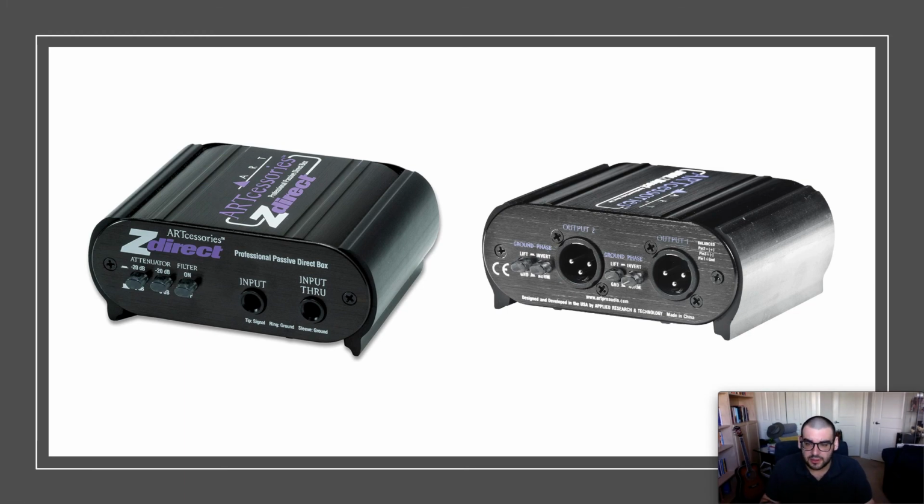you don't want the noise of the cable. Okay, and if you have long runs of cables, you want to use a direct box, because what will happen, or how you set it up, is you would plug in with your guitar here using a 1/4-inch instrument cable or TS cable. On the back end, okay, this would be very close to the performer, by the way. On the back end, you would have your much longer, long-run XLR cable for the output that would then travel all the way to your mixing board, which might be quite a ways away, especially if the performances are way far away and the engineers and the sound people are behind.